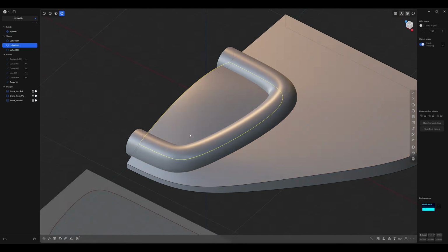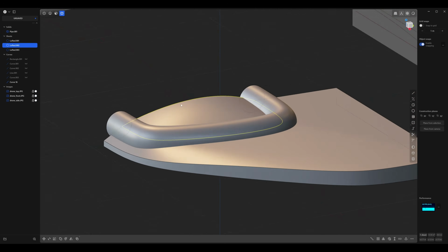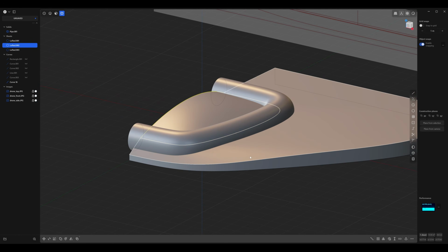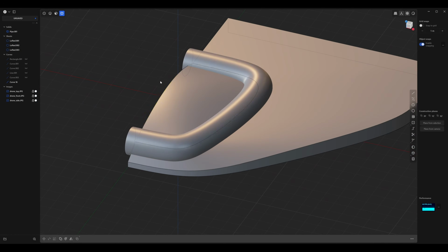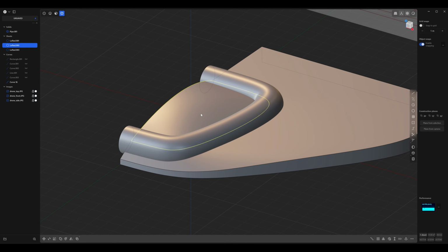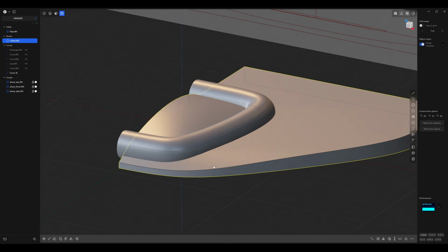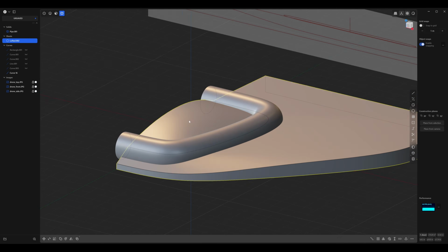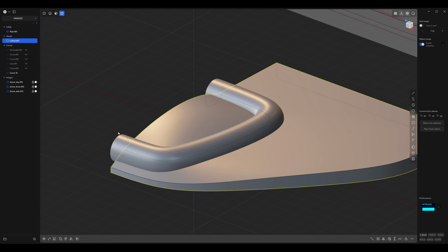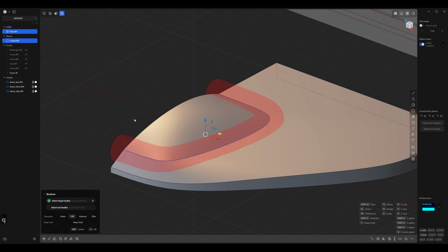So you can Boolean these individually, or you can just connect these surfaces and Boolean them once, which is what I'll do. So I'm going to select the canopy, shift select this main surface, and this one, why not? Press J, and now they're joined as one surface. Next, go ahead and shift select this pipe and press Q.